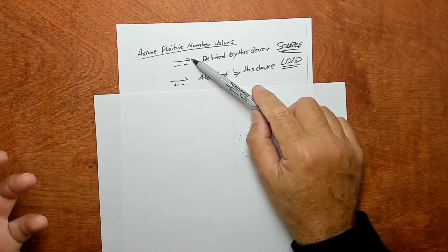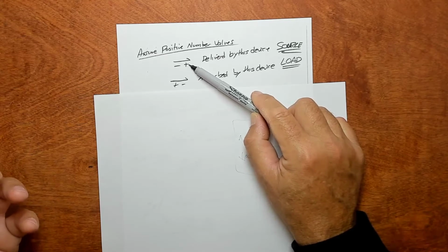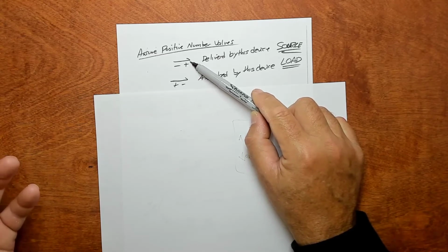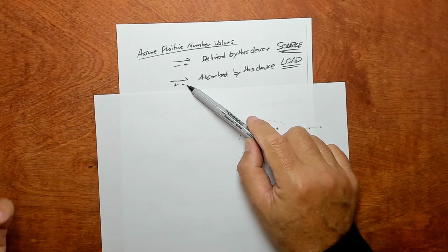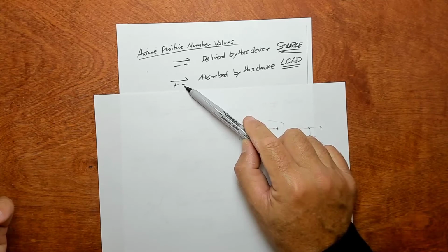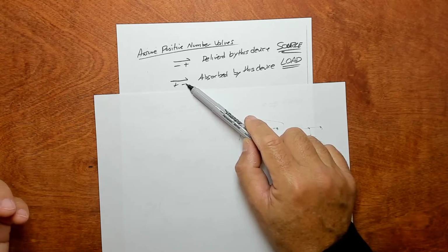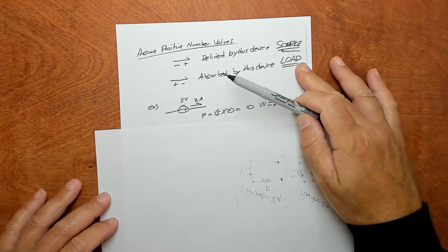Okay, so it must be a source, because the device has these two polarity orientations. It must be a source. It's supplying energy to the system. Okay, if it has this orientation of polarities, that's why the term polarity is useful to talk about both of these together. If it has this orientation, that is, the current is coming out at the negative voltage terminal, then it's coming out with less energy. So that device must be absorbing energy from the current stream. So that's a load.